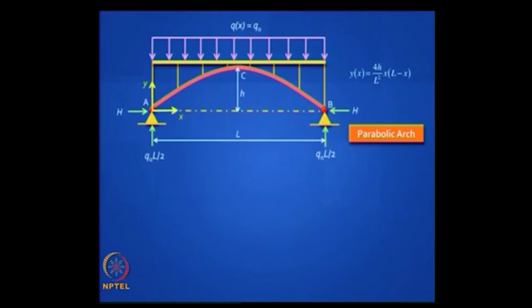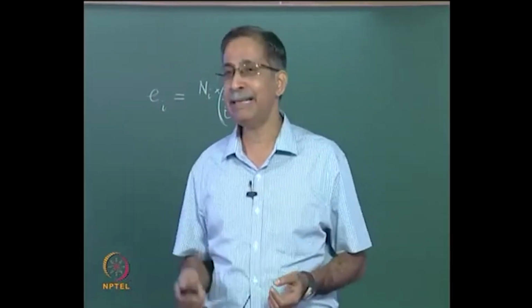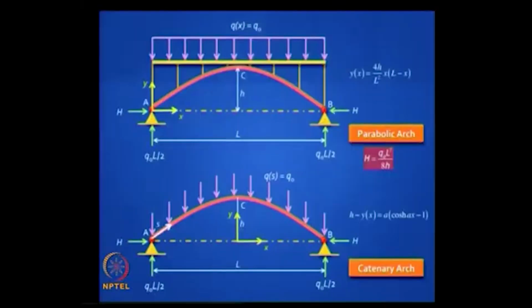Where do you encounter these arches? In bridges, yes, in bowstring girder bridges, but you can also encounter them in buildings, and I will show you a picture where we did this. Okay, in entrances. Now this is a two-hinged arch which is funicular. The boundary conditions are not important, so if you have a uniformly distributed load along the horizontal span, the parabola is the ideal shape.